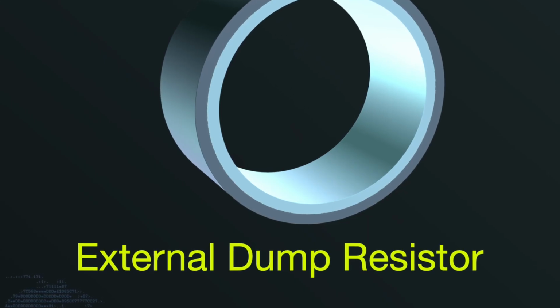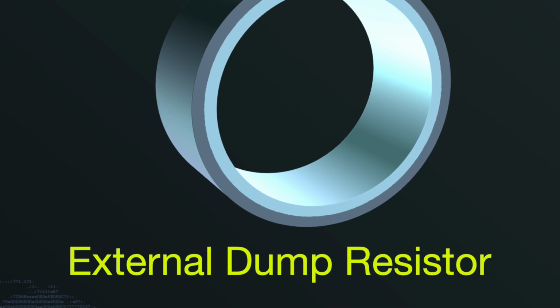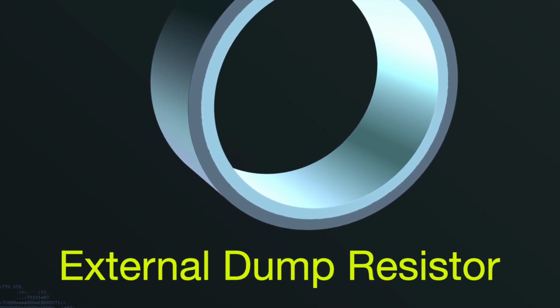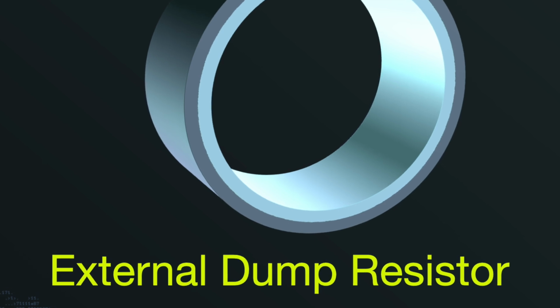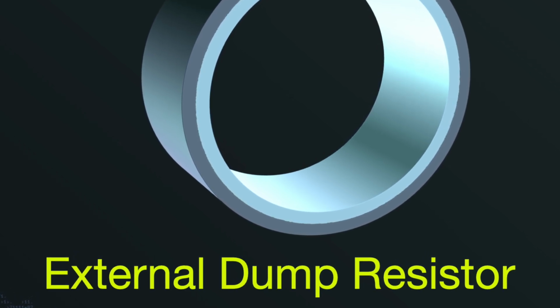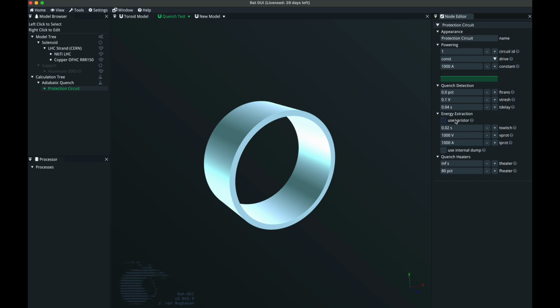Let's go to the most simple case first. And that is when after you have detected a quench, you switch in an extraction resistor or a dump resistor. And that's here in the next bit. This is called energy extraction. There you can also use a varistor, but that's the next case. So let's first look at when we have just a normal resistor that is switched in series with your coil after your quench has been detected and your signal processing delay has passed.